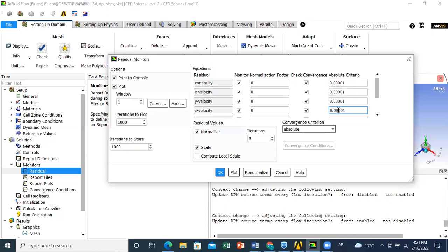When you build a CFD model and compare it with experimental data, you can set what are the good conditions to give you converged results. And when you set your methods and your numbers, you can use the model you built to simulate new parameters, to conduct a parametric study, etc. So this is concerning the residuals.